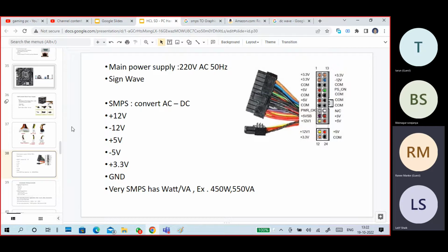How much power is required to run these devices when you start your computer? For example, a CPU consumes 55 watts, RAM consumes some 2 watts, just the wattage and not kilowatts. Total overall wattage consumption is, for example, 300 watts. Now you want to buy an SMPS for 300 watts, so purchase a 350 or 400 watts SMPS.